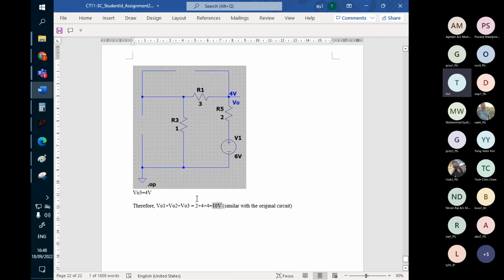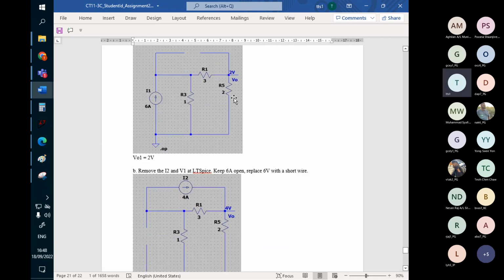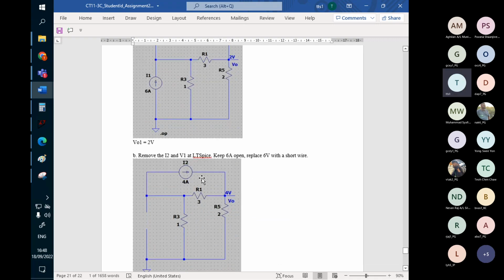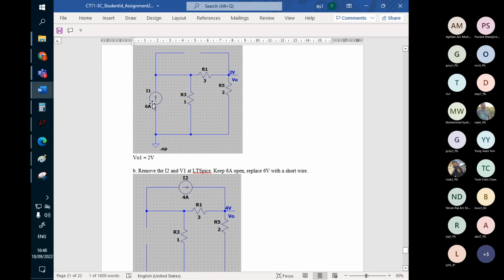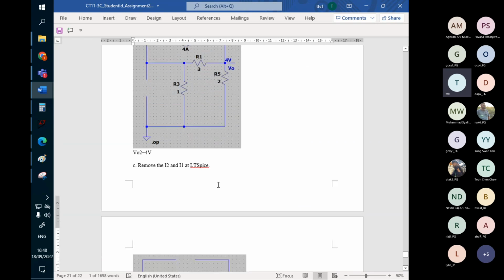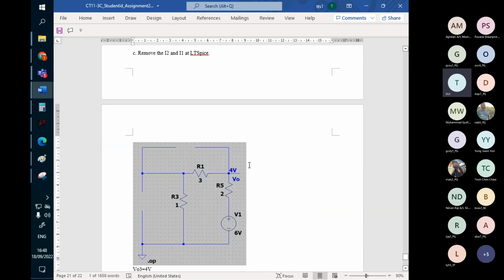Even though we have to do it 3 times, this is for circuit analysis. I mean, when you use a piece of paper, if you can throw out these two sources, leaving only the current source, it's easier for you to analyze it. With only one current source, or only one voltage source, it's easier for the user to analyze.